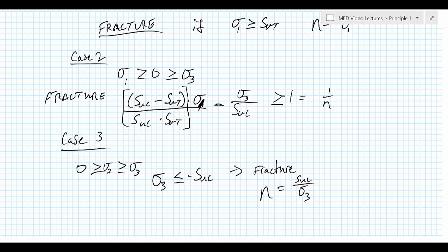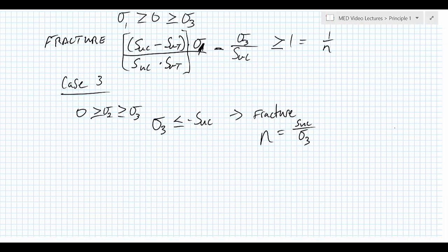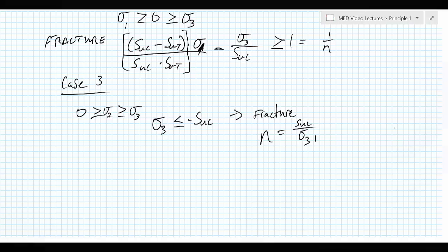Not all materials are always ductile or always brittle. They can change. So for example, steel can be very brittle if it has a high sulfur content, or if the load temperatures are very low, or under high impacts. Those can all be situations where the energy in it will cause a crack to grow, as opposed to plastic deformation. Well, that'll about do it for our brittle failure theories. Until next time.